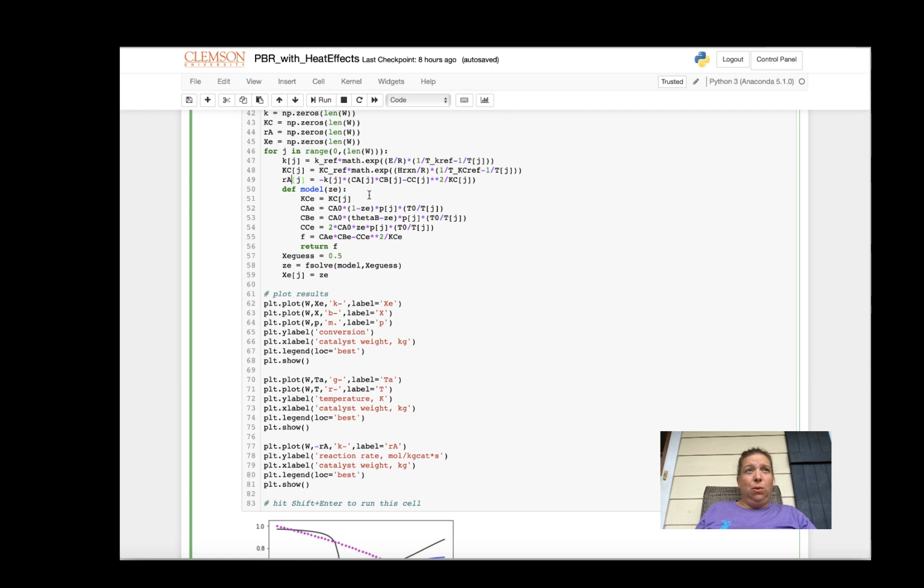So I could manipulate that algebraic expression and come up with an expression for the equilibrium conversion. There is just too much complexity there, given that there are squares, temperature changing, and pressure drop terms, that I do not trust myself to do that algebra without making any mistakes. So instead, I'm going to set this up as an equation, and I'm basically going to use this fsolve function.